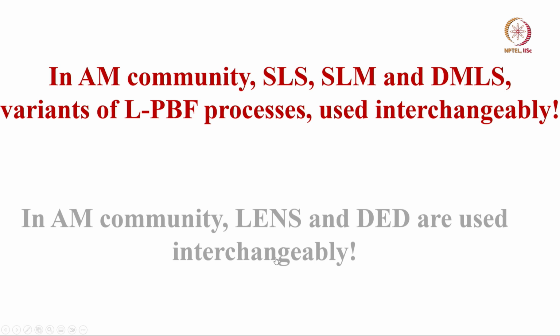In the additive manufacturing community, SLS, SLM and DMLS, selective laser sintering, selective laser melting and direct metal laser sintering or direct metal laser melting, are all variants of LPBF processes, laser powder bed fusion processes, which are used interchangeably.